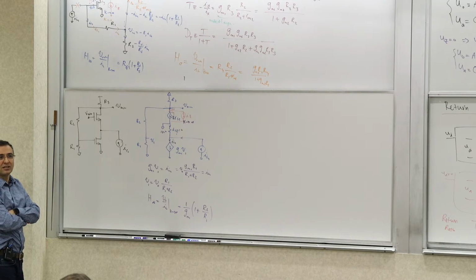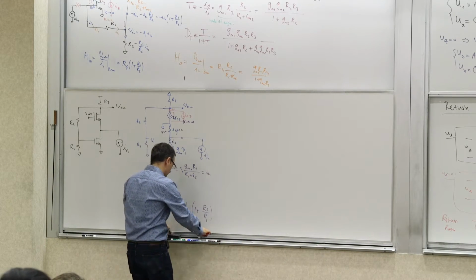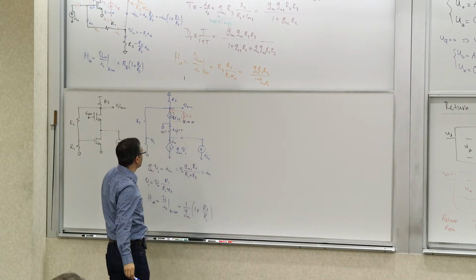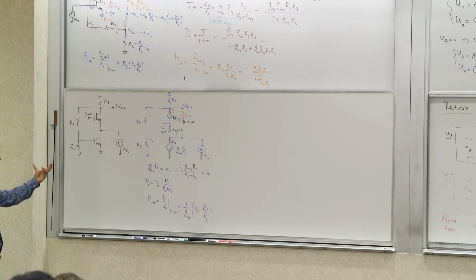And IZ, again, never enters the calculations. Never. Or VZ. It never enters. So if you had a VZ or IZ in there, you're doing something wrong. It's just a way of showing it without changing the drawing into funny-looking schematics.